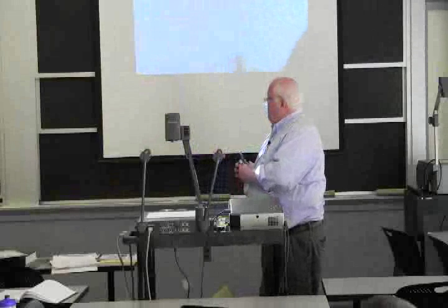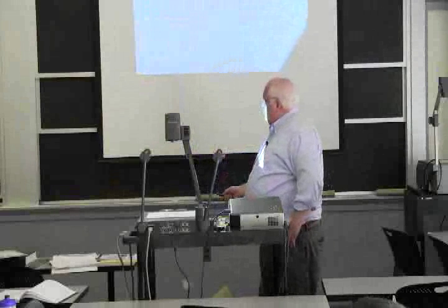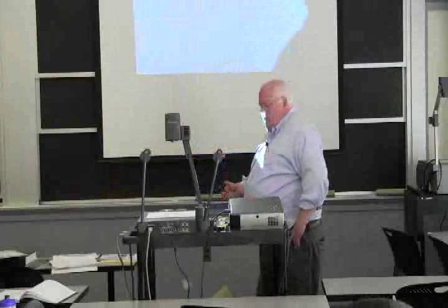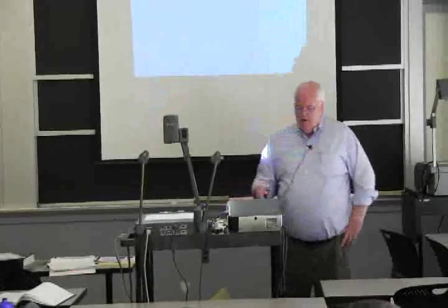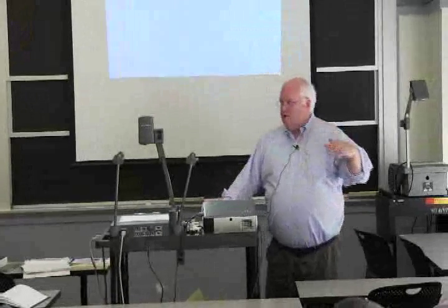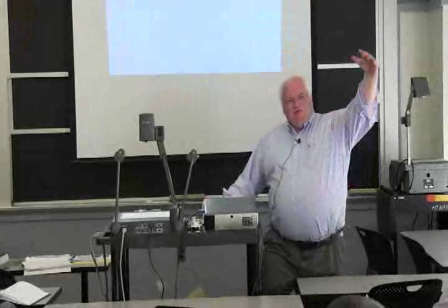So anyway, okay, getting back to casting technology. We talked about as much as I want to talk about extracting the heat of fusion. I do want to say something about shrinkage. One of the advantages of continuous casting is you don't have to cut off a riser. All the shrinkage just gets pushed to one end.